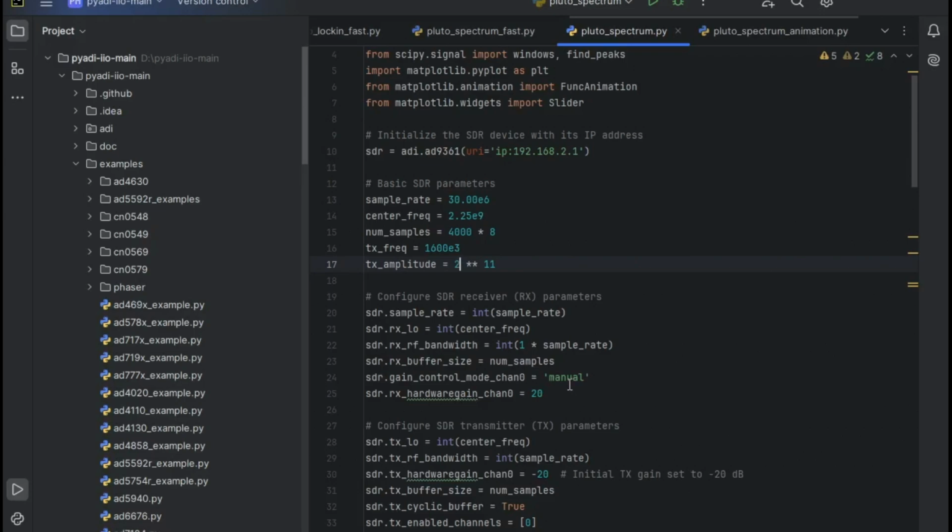But in some scenarios, you don't want to use the fixed gain settings. What you want is to have a certain power after your VGA, or your variable gain amplifier, no matter what you have at your input. So the gain of the amplifier needs to change all the time to make the amplitude after the variable gain amplifier equal to the value that you define.